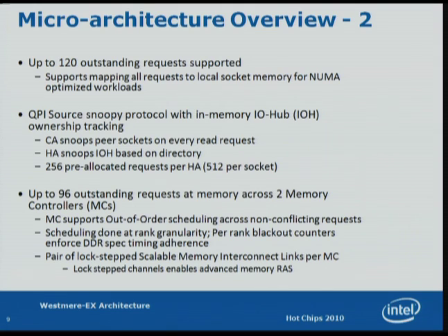Now on the memory side of things, we can have up to 96 transactions outstanding at memory. The memory controller itself supports out-of-order scheduling. It schedules at a rank granularity, and it hooks up, like I said, to the high-speed scalable memory interconnect. And there are 2 channels that operate in lockstep, and the lockstepping really lends itself to several advanced RAS features such as single device correct and double device correct that I'll touch upon in some follow-up slides.